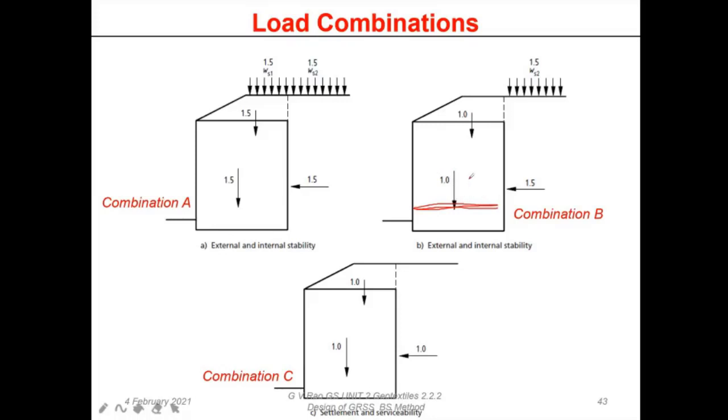It will be sigma tan phi. Sigma is the vertical stress. Tan phi means, in this case, phi is equal to delta; the interface is going to be the delta angle. So we are going to think of sigma tan delta as the frictional force which is going to act along this.